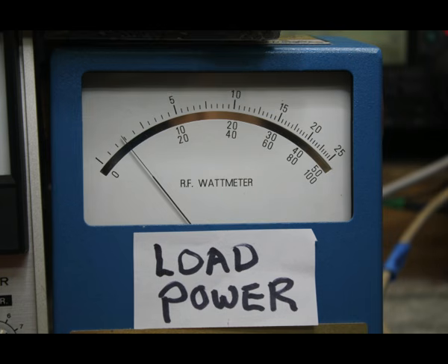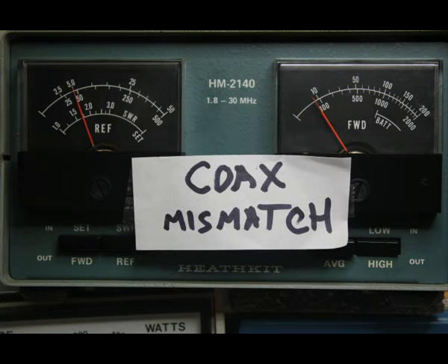I'm just showing you that if I don't match at the transmitter, things look pretty bad as far as power delivered to the load. So if we look at the Heathkit HM2140 meter, which is at the load end of the 25 feet of LMR 400 but ahead of the mismatch network, so it sees the high SWR at the load end of this test setup, we see somewhere around 19 watts of forward power and 15 watts of reflected power, someplace in that rough area. Now these meters get a little bit off when they're running into such a mismatch impedance, so we can't rely on them exactly.